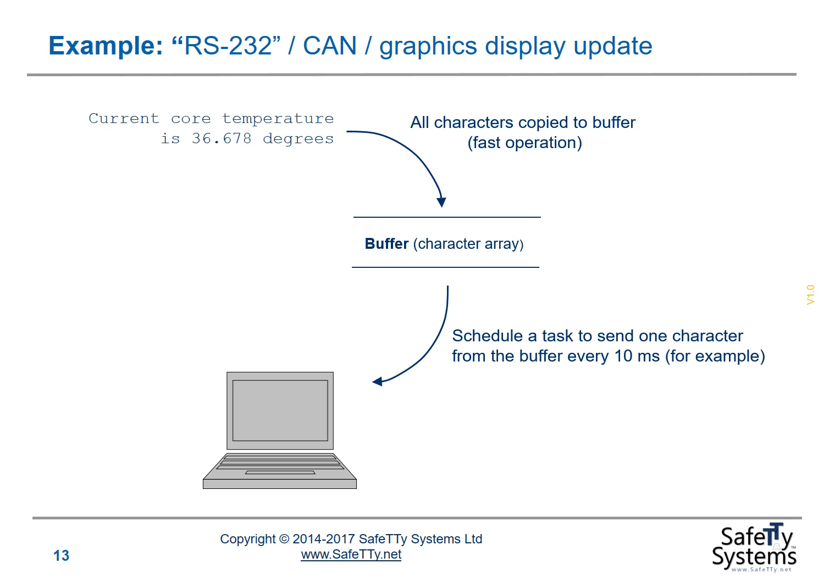So I don't have to wait for that buffer to be released. I know that if I schedule the task to send the characters at a sufficiently long interval, the UART buffer will be clear by the time I pass it the next character. There's no waiting, and my overall CPU load here is virtually zero.